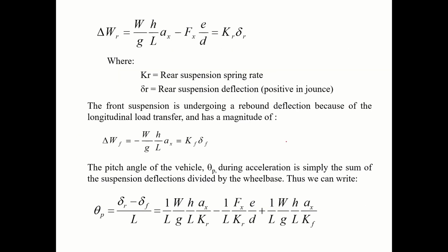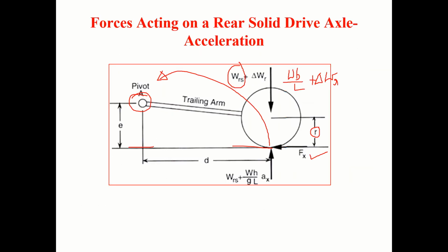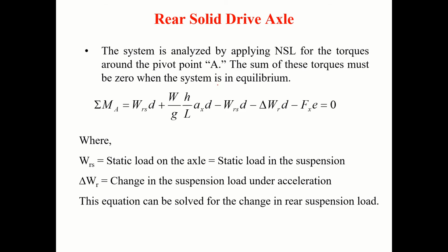One more thing, also Fx into E, clockwise. Because of this load, there is a clockwise moment. These two clockwise moments and this counterclockwise moment, we'll equate to 0.